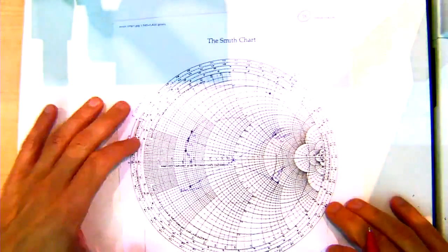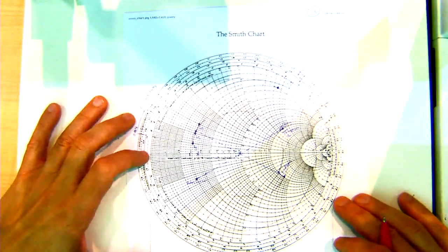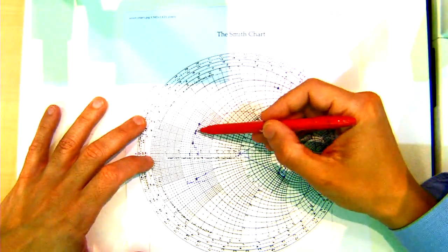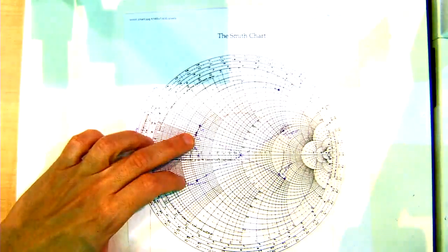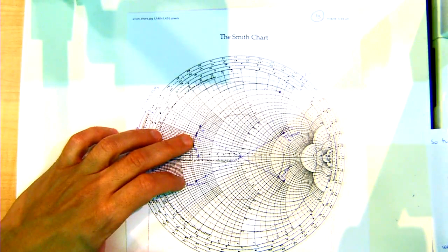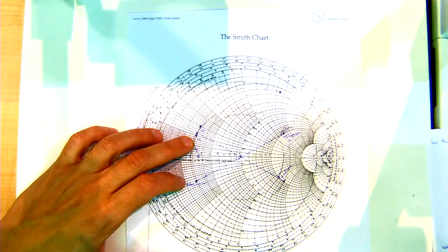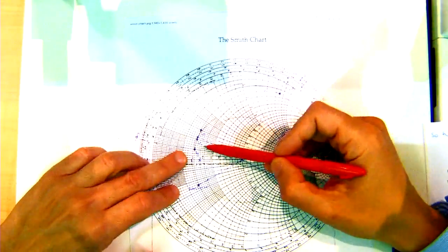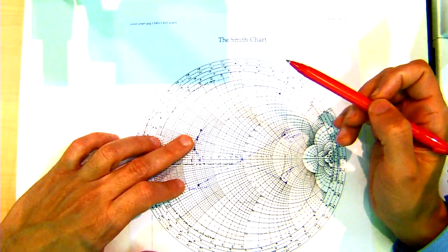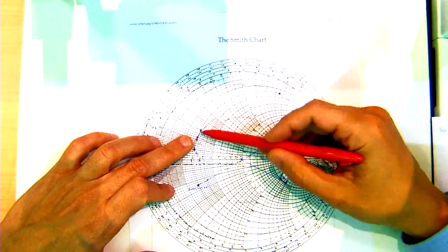So in this example, you start off with a particular impedance, and then we add, for example, 0.44 lambda. If that's a particular value at 2 gigahertz, at 1 gigahertz it's the equivalent of 0.88 lambda, right? So therefore, you find the point and you move across in order to find the effective length.